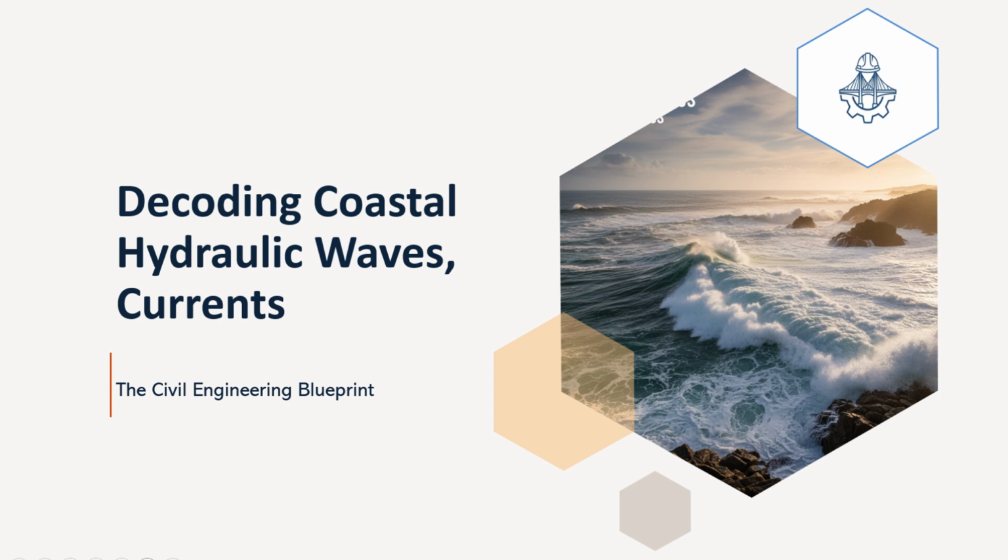This process can lead to significant management problems like chronic erosion threatening infrastructure, beach starvation, or navigation channels filling in with sand, harbor infilling. Understanding and quantifying littoral drift is crucial for designing coastal structures like groins or detached breakwaters, or for planning effective beach nourishment projects.